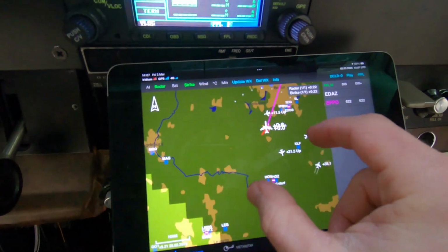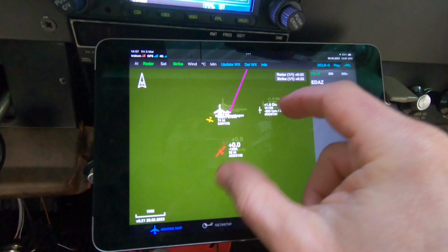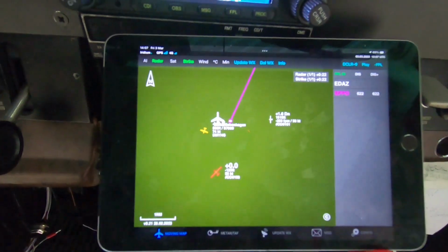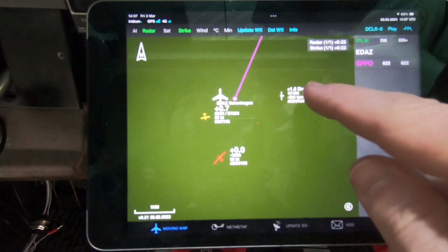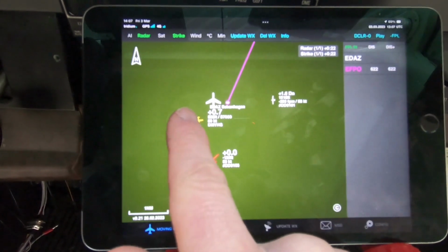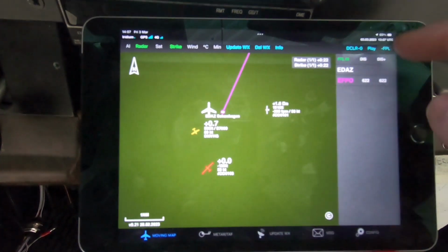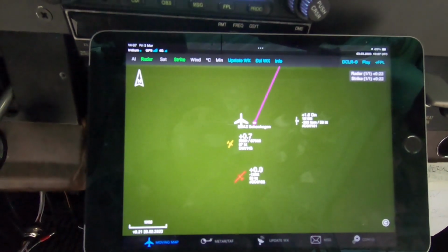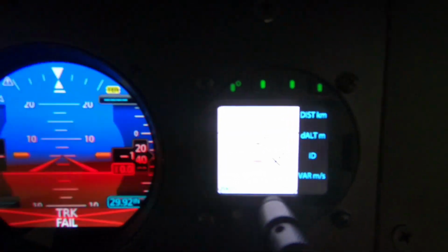of the AT1 device. For this purpose, there is also an RS-232 wire between the ADL installation and the AT1, which transmits this traffic information. And then the link to the G3X is on the wireless FISB. It's actually doing TIS-B over the same link, so it gets all the traffic information.